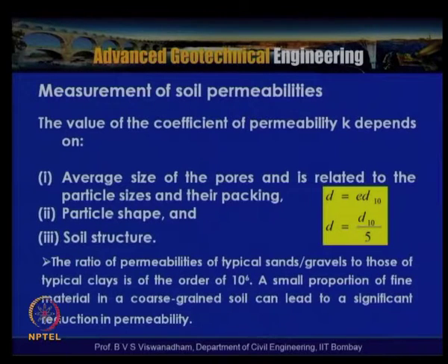Permeability also depends on particle shape, particularly whether it is angular, rounded or sub-rounded, and on the soil structure, that is the arrangement of the soil particles, whether it is a flocculated, dispersed or bulk structure. It depends upon whether it is a loose or a dense packing in case of bulk particles. The ratio of the permeabilities of typical sands and gravels to that of the clays is of the order of 1 million times.